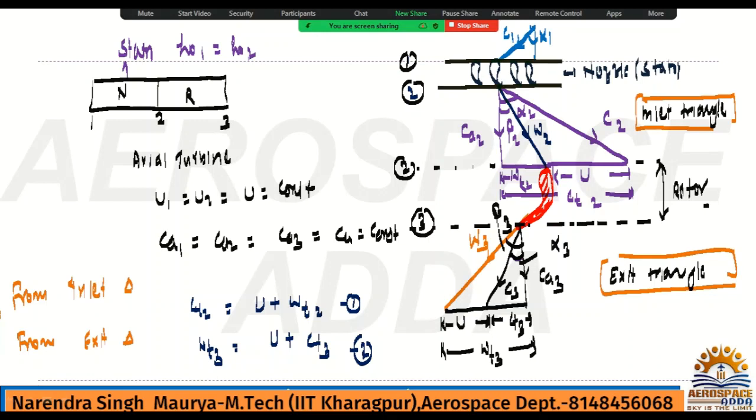And similarly, in terms of pressure also, the total pressure will be constant across the nozzle, because it's not doing any work, and we are considering that the process is frictionless. So if it is a frictionless process, then P01 is equal to P02 across the stator.